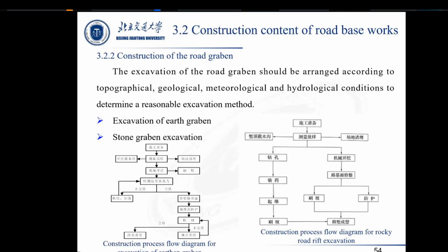The rock road cutting is excavated in the following three ways: for hard rock, weathered rock, and soft rock with cracks, small square stone sections are excavated with mechanical methods and small blasting. Large stone sections and layers use light, split, and deep hole loose controlled blasting techniques.